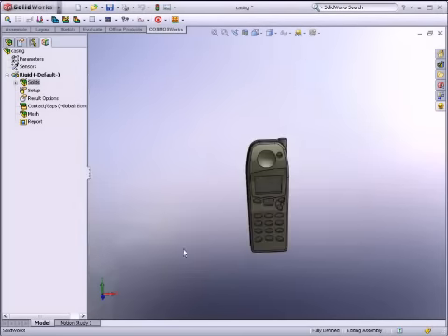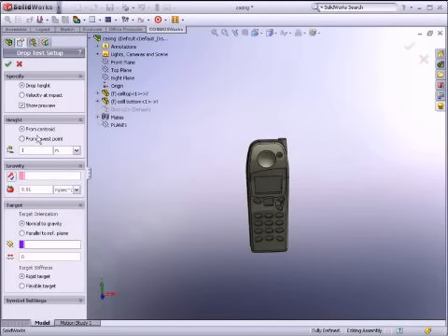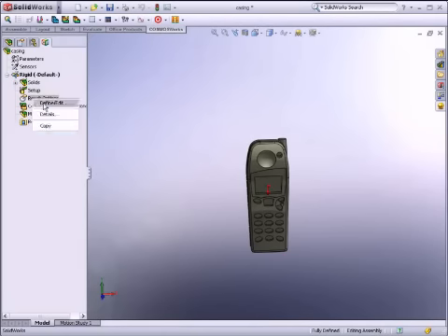Having assigned a material to the model, we now define how the phone is dropped. Here, we are able to set up the drop test using the distance it falls or by how fast it is traveling at impact. Also, you can define the plane of impact and the direction of gravity. In this case, the target will be a rigid floor.